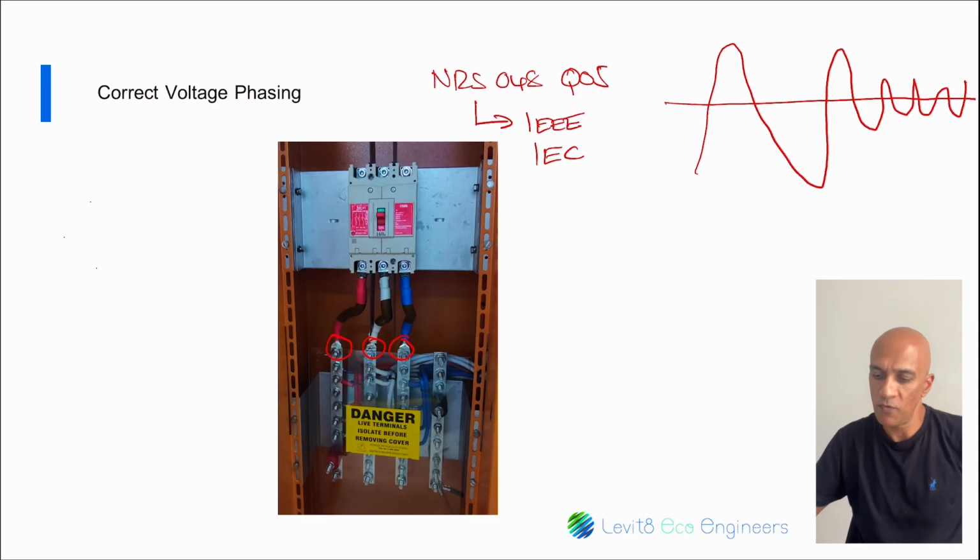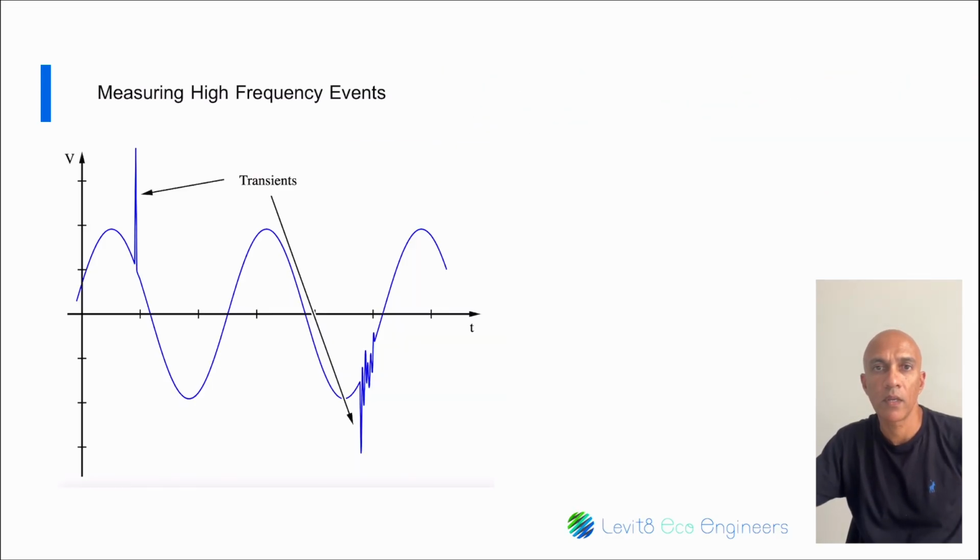Now, a very common one is voltage spikes. These result in the failure of sensitive equipment or lighting. In this case, you would need an instrument capable of capturing a few hundred samples per cycle. That is a sampling rate in the microseconds. Instrument presets usually have the correct range for data capture speeds for whichever parameters you want to measure. So if you are measuring spikes and you select that option, the instrument will be able to capture very high frequency events. You may need to specify an upper voltage limit to trigger the recording.